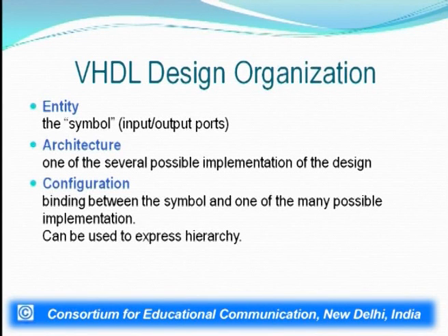Now, when organizing a VHDL design, there are a few parameters, essentially 5 parameters that are to be considered. First one being the entity, which indicates the symbol, and can be considered as a black box, wherein some input connections are coming in and some output connections are going out. These inputs and outputs are referred to as ports. This gives us the external view basically of the circuit under consideration.